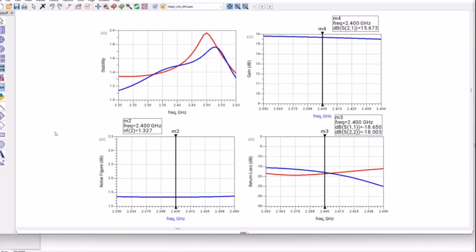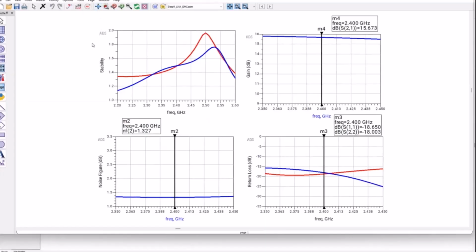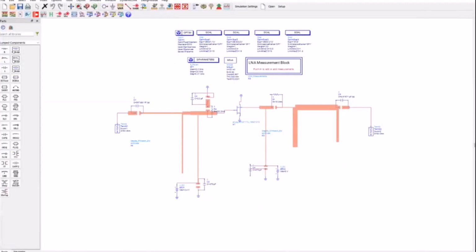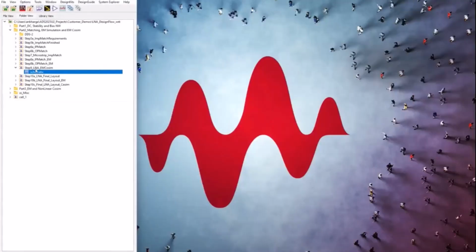So lower the noise figure minimum you can choose for the device, more headroom you will have to guarantee to meet the specification which you are looking for, unless you mess up your design in a very bad manner. So I would prefer still have like 0.3, 0.4 dB inherent device noise figure, and that will give me very high headroom.